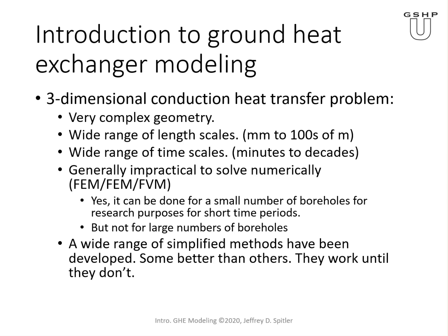We've also got a very wide range of time scales. If we're looking at the response to, say, a change inside the building, a heat pump turns off or on, the response from the ground will happen in a few minutes. But at the same time, the ground has such a large thermal capacity that the heat buildup, or cold buildup, could take decades. So we have this very wide range of length scales and very wide range of time scales.